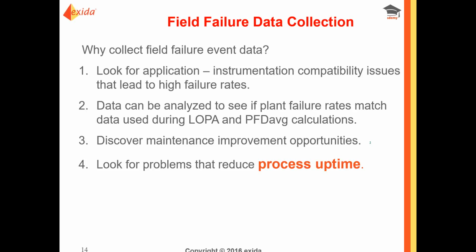And what that really boils down to is process-wetted instrumentation, sensors and valves, and often it's a matter of materials incompatibility with the chemistry of the process. I've seen pictures of valves that have been eaten away. I've seen pictures of diaphragms in pressure transmitters that are shattered.